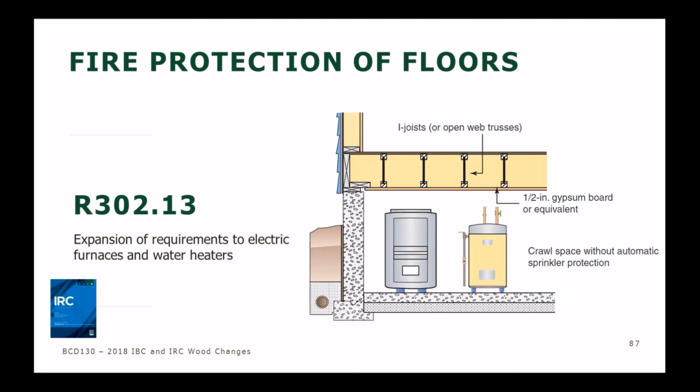Anytime you have wood trusses that aren't fire retardant protected in some way in that space or tested to be equivalent to solid sawn lumber, any sort of I-joist or thinner than 2-inch wide composite member that's going in there that hasn't been tested or isn't fire retardant protected.